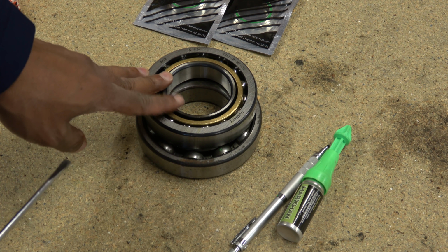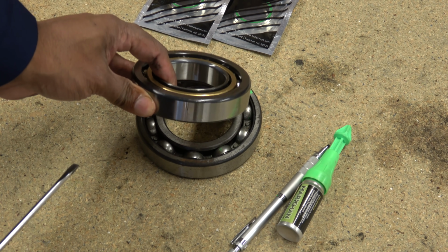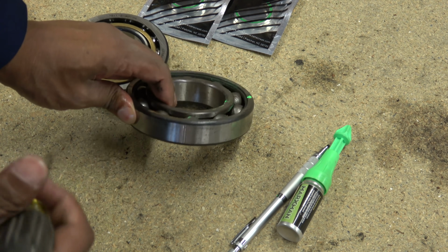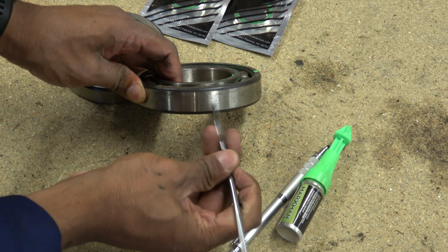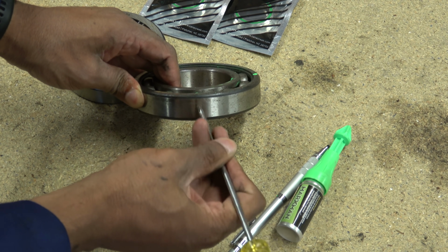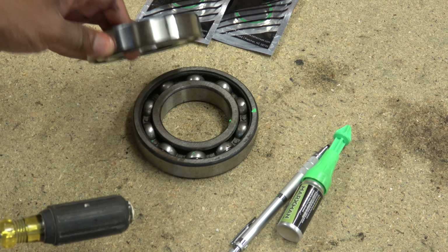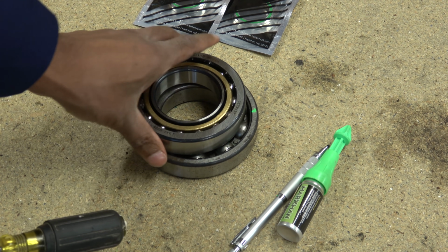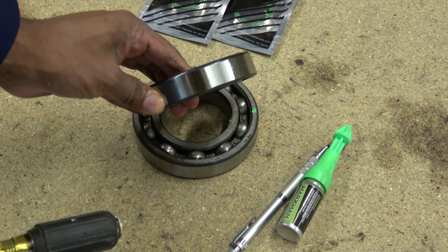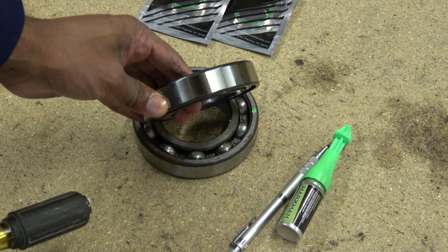Now one of the things about bearings is all of them, all the decent ones, are hardened. So if we get the failed bearing and a screwdriver and try to mark it, it's almost like it's running on glass. It won't even touch it. So when you put that bearing into a bike frame, you need to make sure that it doesn't move about, because if it starts to move about and wobble, it will totally trash the bike frame.